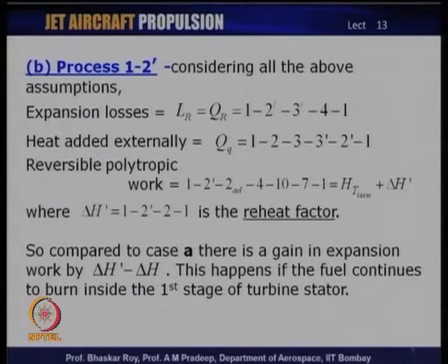This also opens up the possibility of reheating between the turbines or interheating between the turbine stages. After the HP, as you know, the flow loses a lot of its energy in the process of doing work, and there is a provision now that if you manage to do a little bit of reheating between the HP and the LP, before it hits the LP, you can now expect to get more work extraction from the LP than before.